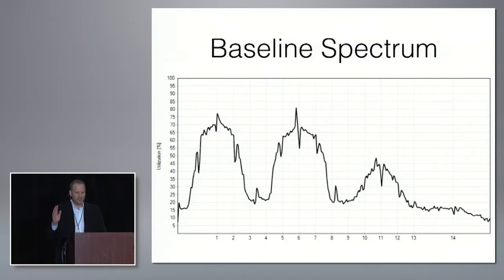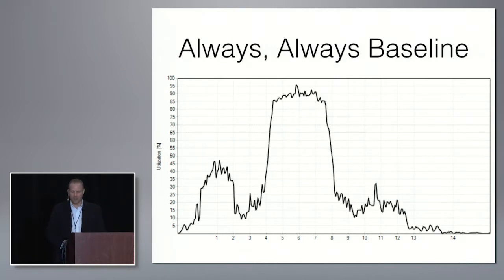Remember I said how important it is to baseline? It's not only important to baseline as you're starting your test, but before each one of your tests. We were in a situation where we went up to start another set of collection, and we turned our analyzers on, and we were getting this. The channel utilization had jumped up to 90%. So needless to say, there wasn't going to be too much working in that situation.